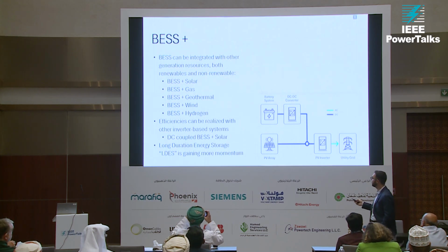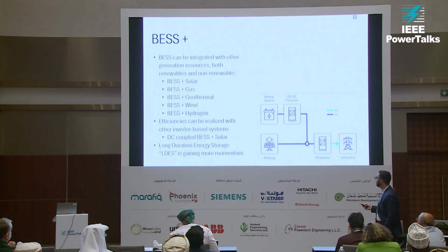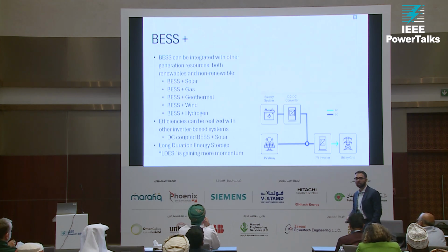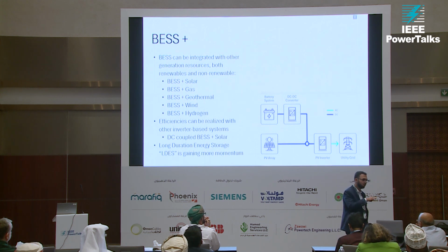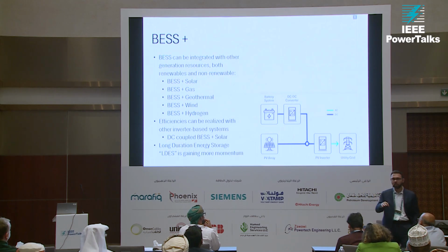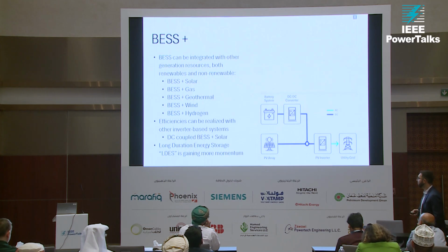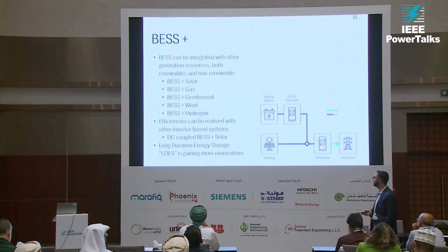We've noticed that BESS plus gas is becoming a very popular installation in North America and Europe. We've done BESS plus geothermal at Calpine. We have a really large geothermal plant, and to have better firm capacity deliverability on that plant, we decided to put more batteries, and that helps us reshape and firm shape our generation profile. We've done BESS plus wind. I don't have it here, but we did BESS plus hydro. We had hydro dams that also installed BESS for similar reasons that I mentioned earlier.